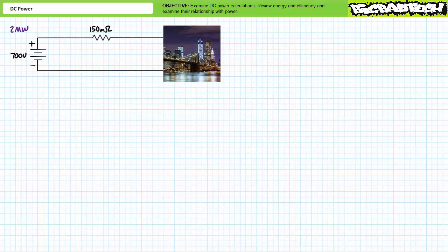In a perfect world, a source would deliver all power to an intended destination with no losses along the way. In the real world, the means of transmission itself extracts a degree of losses. In an effort to minimize losses in the lines, electrical power is ordinarily transmitted from a source to a destination using high voltage rather than high current. Ordinarily, this is done with AC electricity, a type of electricity that cyclically varies polarity and magnitude rather than DC.